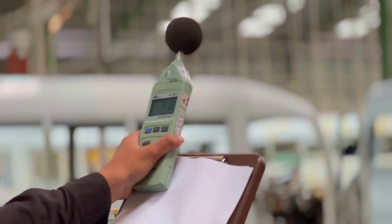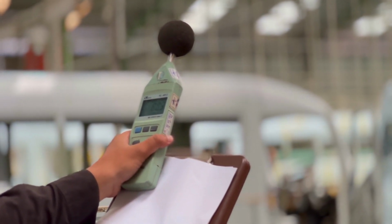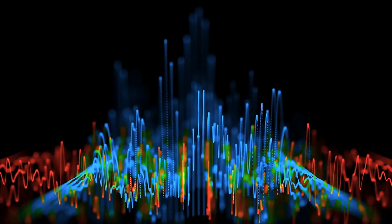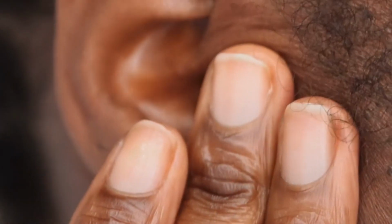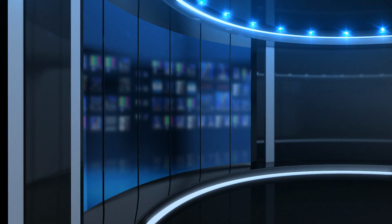Implementing acoustic treatment. Analyzing room acoustics. Before installing acoustic treatment, it's important to analyze the room's acoustics. This can be done through simple tests like clapping hands to listen for echoes, or using a measurement microphone and software to assess the frequency response. Identifying problematic areas will help in strategically placing acoustic treatment for maximum effectiveness. Building DIY acoustic panels.